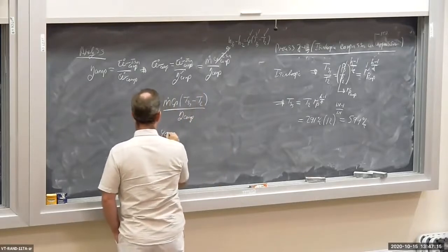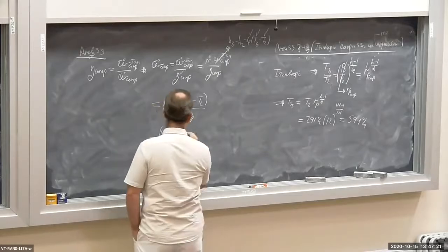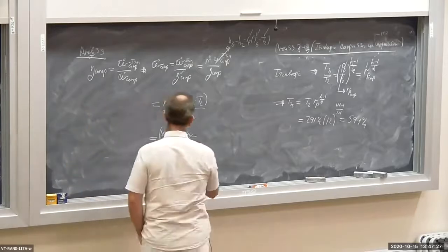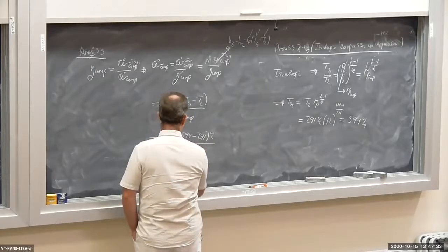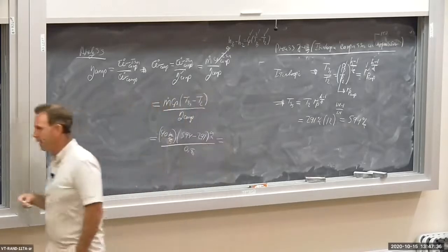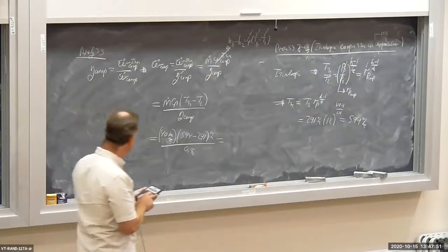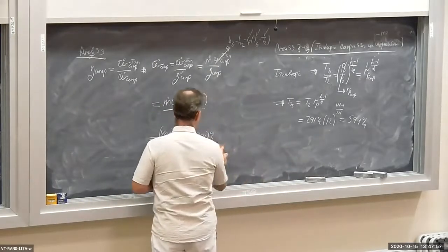So that's equal to 40 kilograms per second times Cp, oh, I forgot the Cp, 1.005 kilojoules per kilogram degree Kelvin, times 594 minus T2, which is 291 degrees Kelvin, and then the isentropic efficiency is 80%.